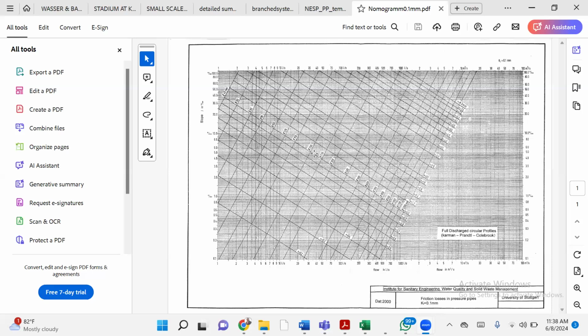So, did you understand it now? It will fall between 2 pipes. You check whether the slope requirement, the velocity requirement, is met. Then moving from right to left on the upper side, it will also fall between 2 pipes. You choose the biggest one, because last week I told you that it's better to over-design than to under-design.